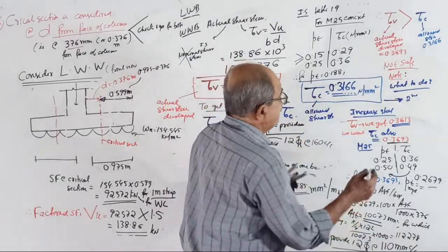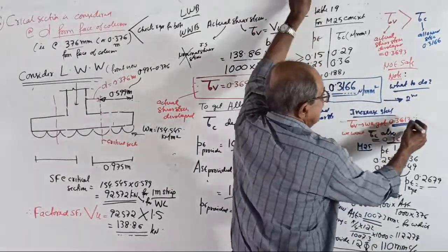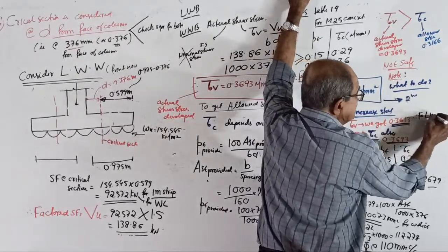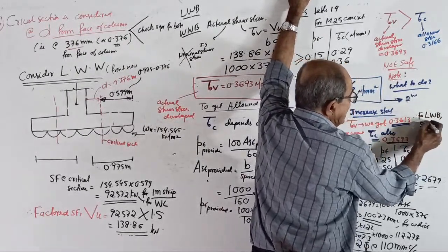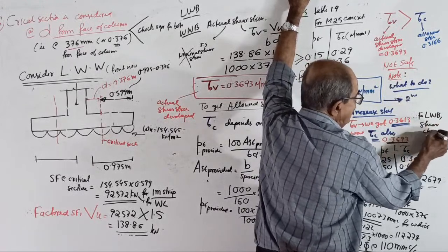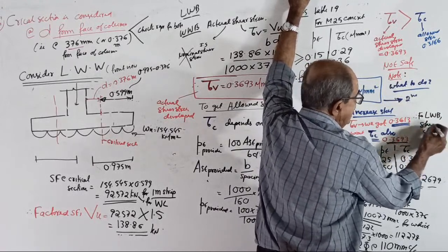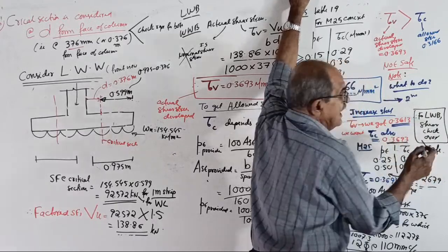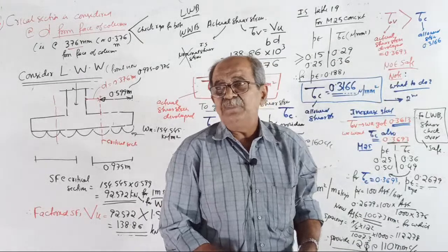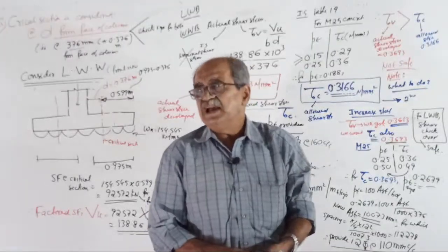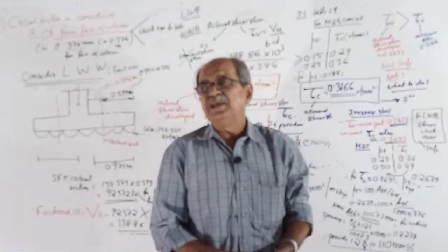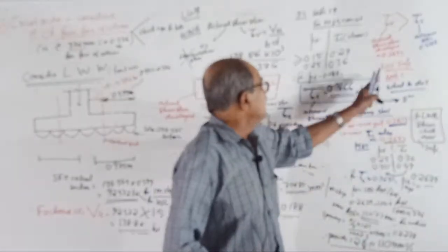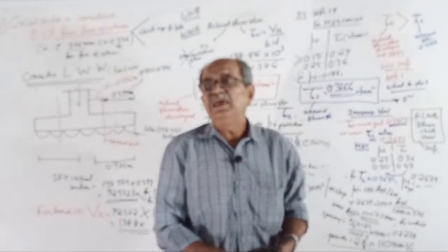All right. Therefore, for lengthwise bending, shear check over. It is made safe. You write there, first it came unsafe. One of the options is increase D, or the second option is what? Increase the steel. Usually when marginal unsafe comes, people go for increase of steel.